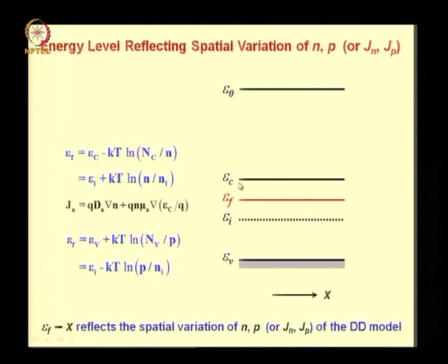When we go to heterostructures where the composition changes with distance, the atomic structure changes with distance, then E naught and EC in general would not be parallel, and therefore a conflict will arise as to whether you should take the slope of E naught or the slope of EC for the electric field on an electron in a semiconductor. So for a conduction electron you must use EC by q.